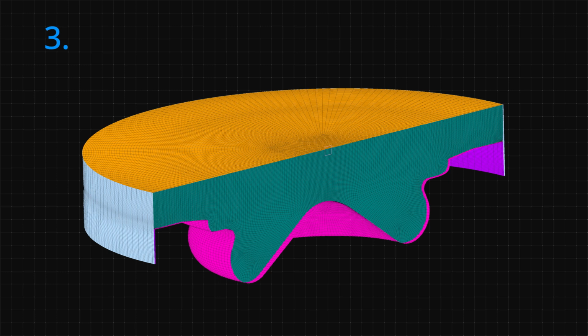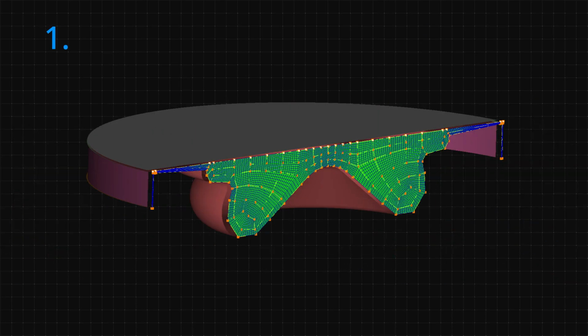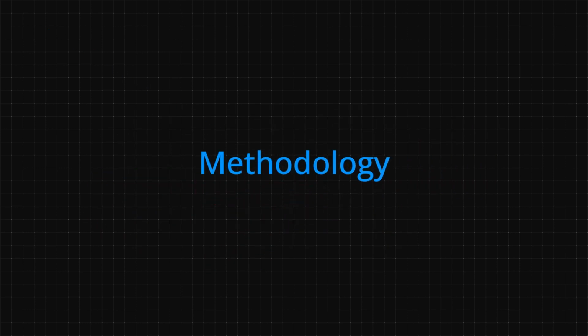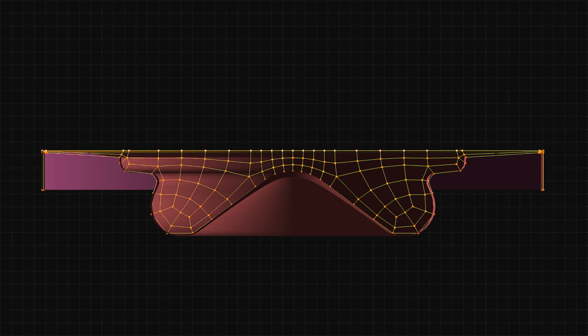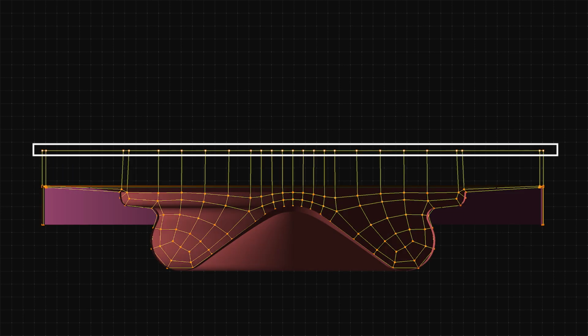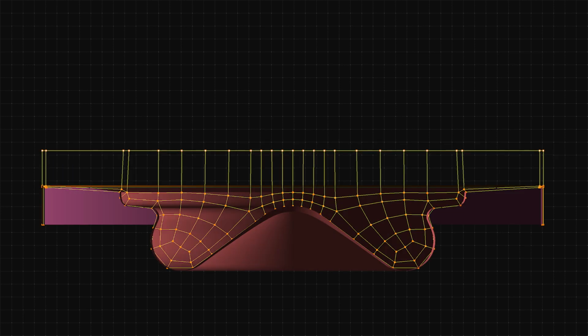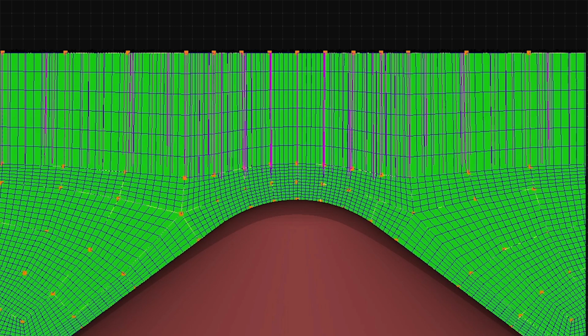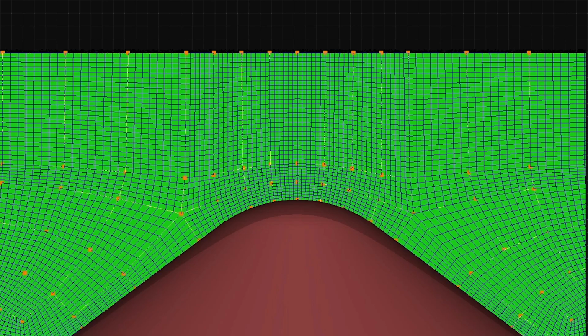This video shows you how to proceed with the first method by moving the respective surfaces and corners in the topology and changing the density based on the change in length. Methodology. In this topology, 2D section shown here for clarity, the highlighted set of edges remain stationary, while the remaining corners move according to the crank angle. As the remaining corners move, the density of all the block edges along the z direction in the last layer needs to be changed according to the change in length.